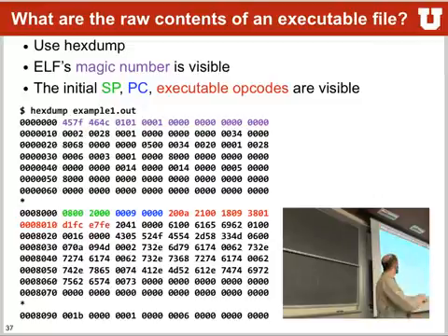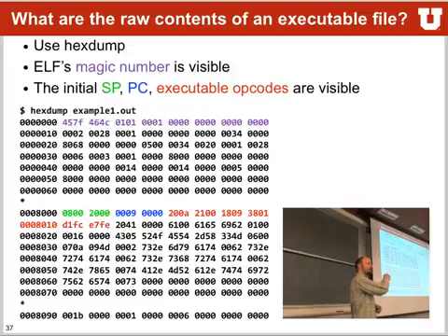And then down here, you can see the same stuff again. Do you notice something? Slightly different than from what we have seen before, right? It's now in half words, little endian. Instead of byte-wise, it's now half word. So we have 2000 and then 0800. Sometimes very confusing to figure out in little endian what's what. Sometimes it's really on per bytes. Sometimes it's on half words. So you have to be careful of what you're looking at.